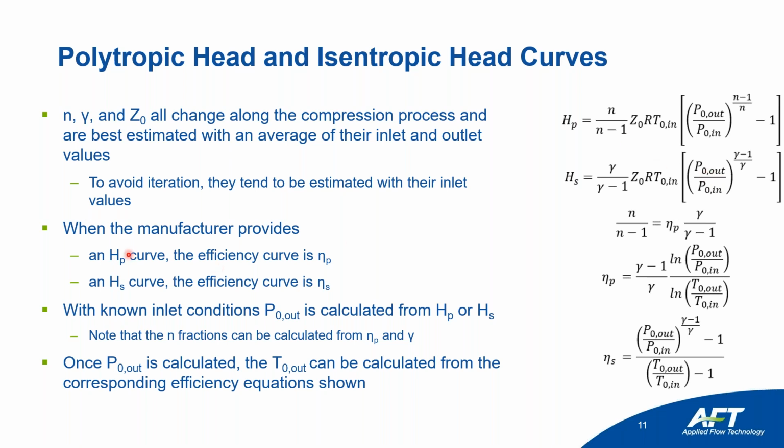I mentioned before that when the user provides that polytropic head curve, then the efficiency will be the polytropic efficiency. And when they provide that isentropic head curve, then the efficiency will be the isentropic efficiency. That's important for these equations.